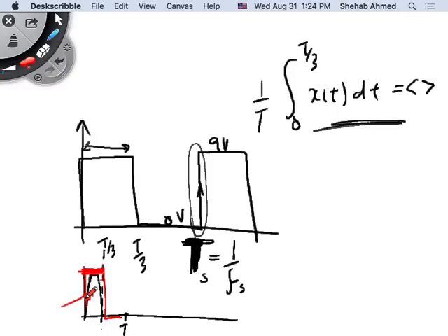So this is what's going to limit your switching frequency. This is one thing that will limit your switching frequency. Typically, you'd like to switch as fast as possible, right? But then you are limited by the switch's rise times and fall times. Not only that, remember we said it takes time for the current to rise. When the current rises across a switch, what happens?